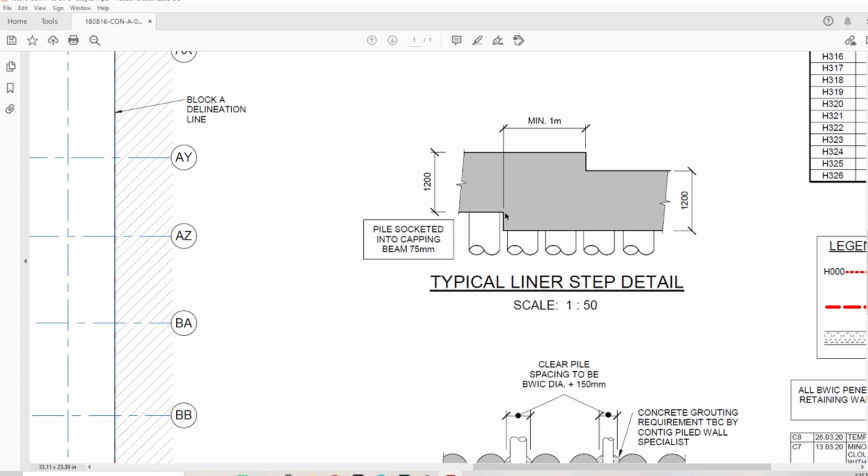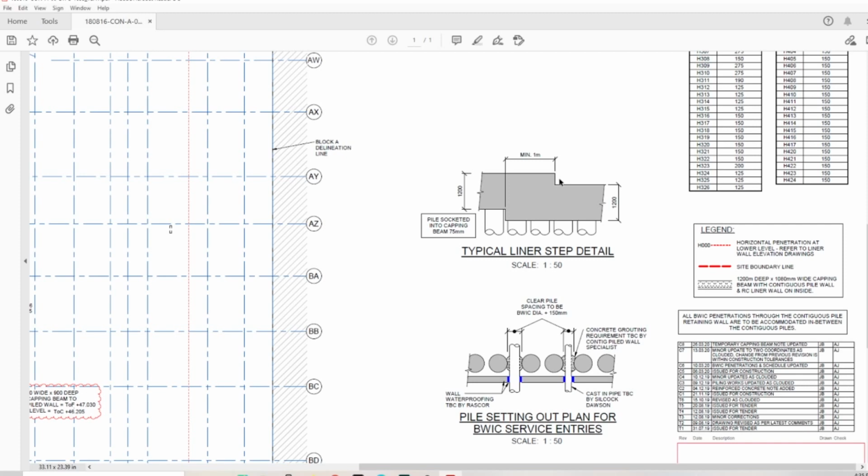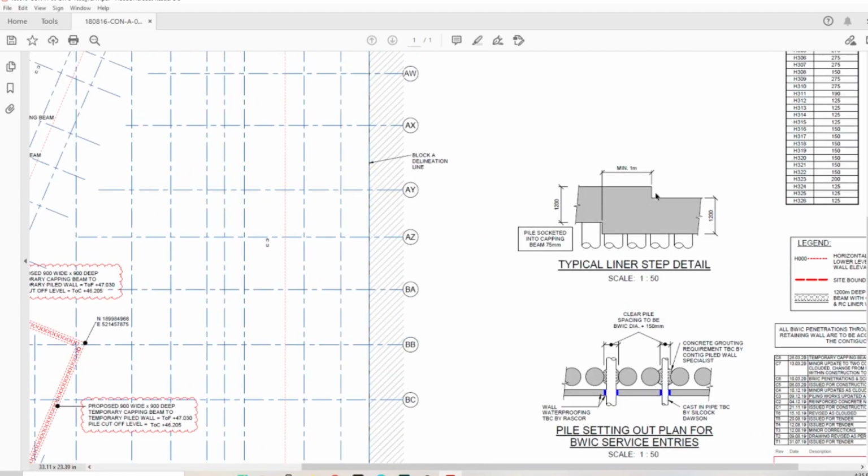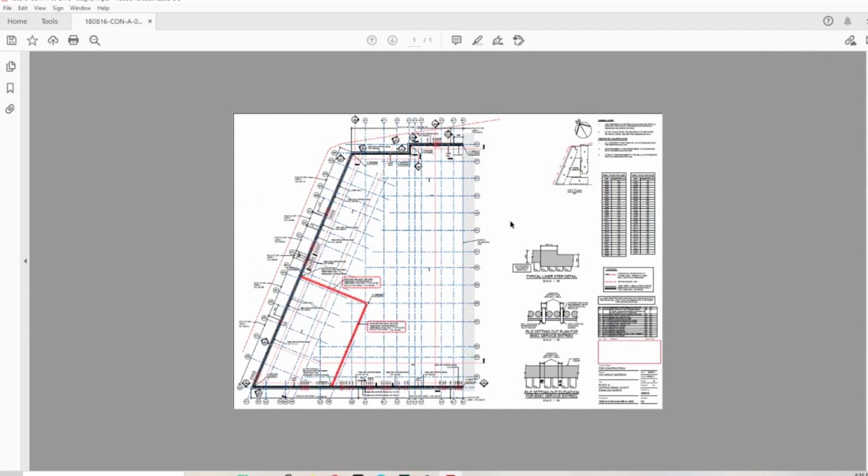This is the dashed line, and that would be actually the line which you're going to be interested in doing all the soffit steps, as this is going to be created later after all reinforcement is done. This line going to be later marked for the shutter, just to create a step on top, but you need to know what's happening below, as this is the first thing you're doing. So that's the GA drawing here.